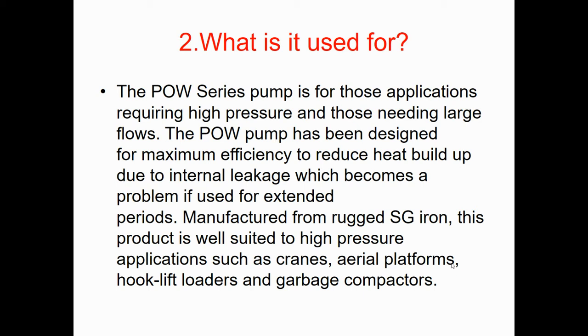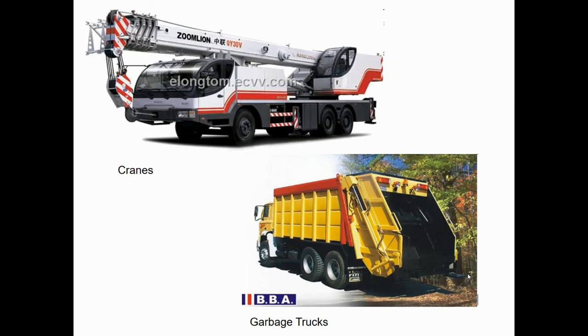What are the many applications where this type of pump is used? For example, how to move the crane. Usually we need to use the hydraulic power, and this hydraulic power requires pressurizing the hydraulic oil, and this can only be achieved by using the gear pump. Same thing is happening in the garbage truck.